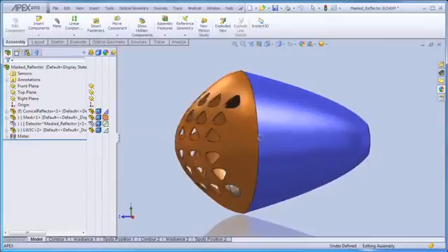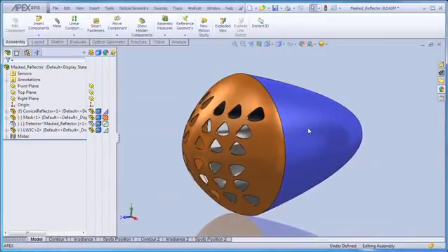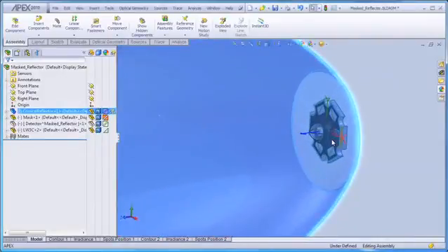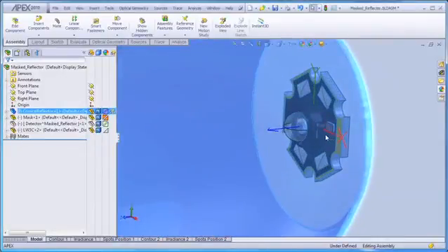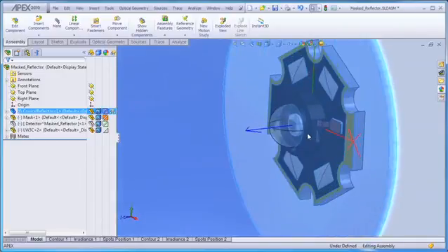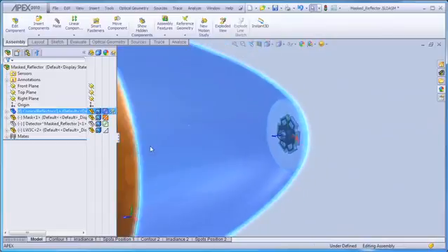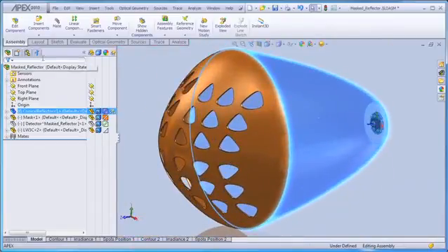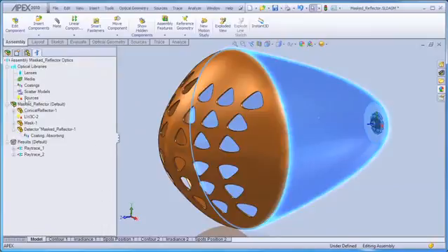Now, using the Apex Light Source Manager, we can quickly insert and position an LED into the model. We can assign total power, wavelength, and number of rays before creating the LED source, and note the level of detail included in the LED geometry. Since we want reflective surfaces, we can use the Apex Coatings Manager to quickly assign an ideal reflective coating to each part in our design.